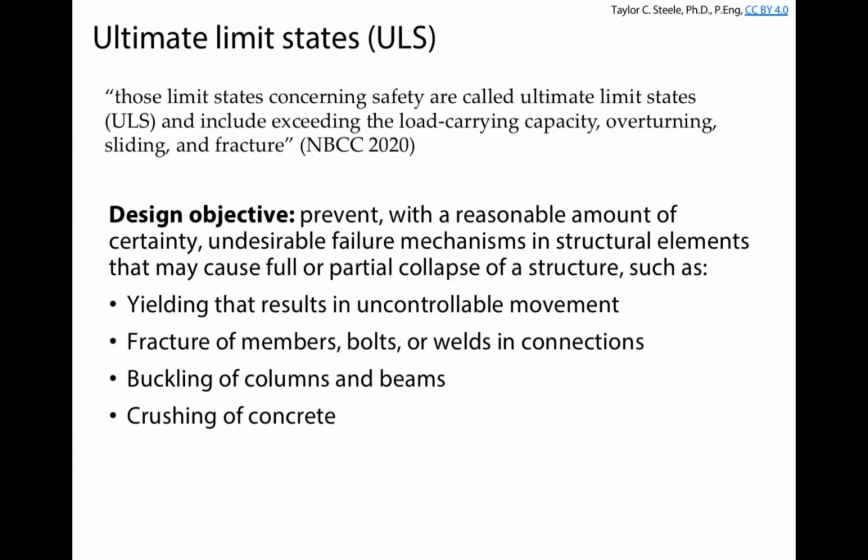We're going to want to prevent buckling of columns and beams. And we're going to want to prevent concrete from crushing. Obviously, our structure is ultimately going to be supported by some concrete foundations. We're not talking about the foundations per se, but we will talk about where the columns meet the foundations and how we can prevent that concrete from crushing underneath the structure.